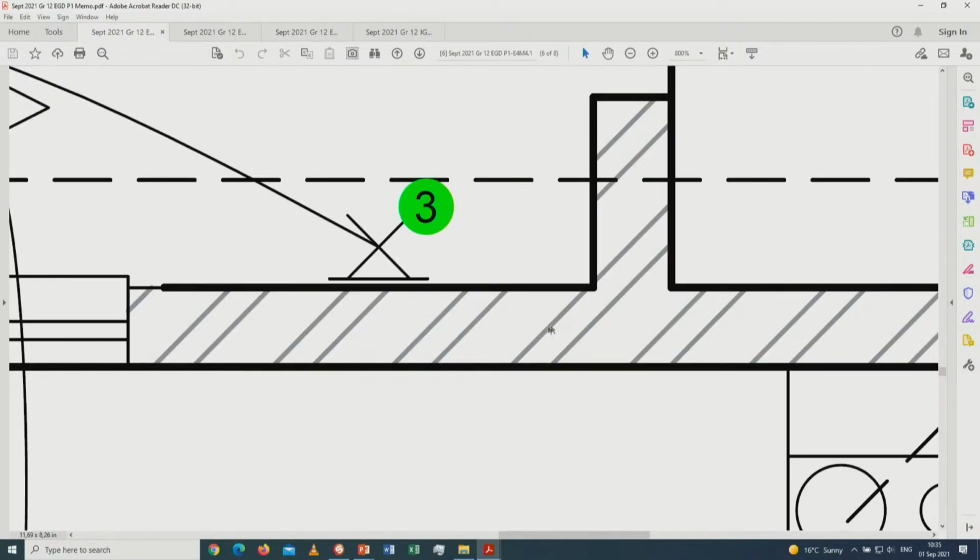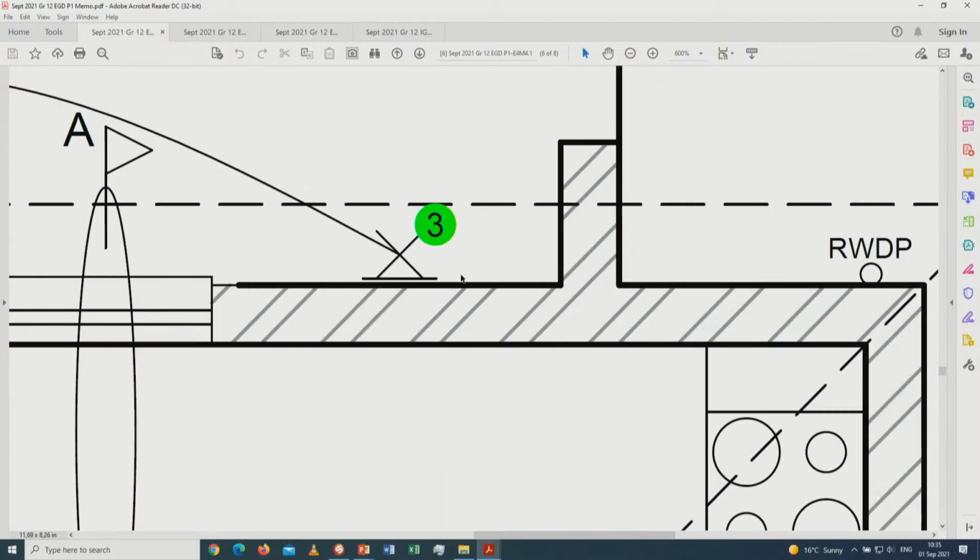Then, of course, hatching. It's not to say it is 45 degrees, it can be 60 degrees, but 2 lines, then a significant distance in between, 2 lines, significant distance, and then 2 lines. If it looks like mechanical hatching, it's not going to get the marks for that.